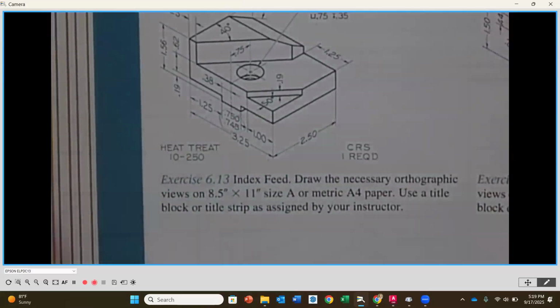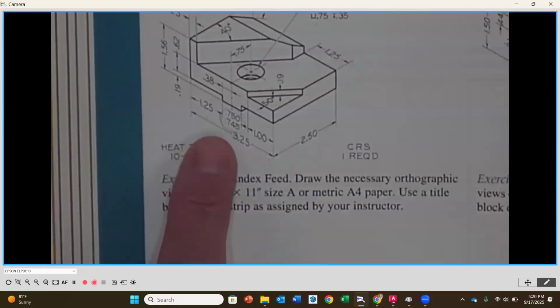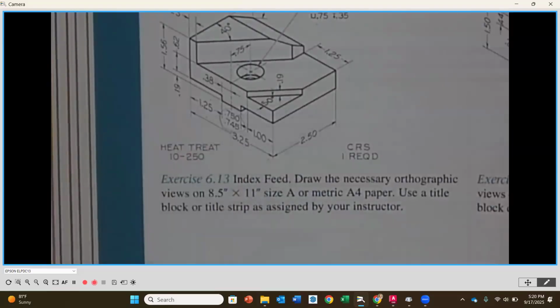Okay, so in this case, we only have a difference of 5 thousandths. A 3-place decimal standard dimension tolerance in our WCTC title block is plus or minus 5 thousandths. So really a total of 10. So this is more accurate than that. All right. So because it didn't fall into the standard title block tolerances, then we had to specify it specifically, which it did here. Okay.